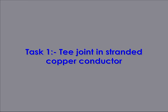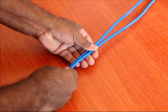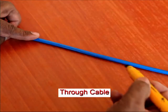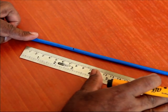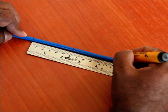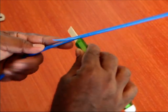Procedure. Task 1. T-joint in stranded copper conductor. 1. Collect 2 pieces of PVC insulated stranded copper cable, 7 by 0.91. Indicate one piece as through cable and the other one as tap cable. 2. Mark the point of tap in the through cable. Mark 60 mm on either side at the point of tap. 3. Remove 60 mm insulation on either side of the through cable from the point of the tap.